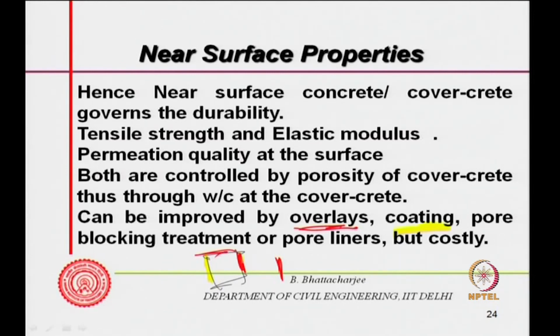Pore blocking treatment or pore liners are actually waterproofing treatments. I might have waterproofing admixtures in the concrete. Also, I can use some material by brush application onto the concrete surface, and this material penetrates inside.